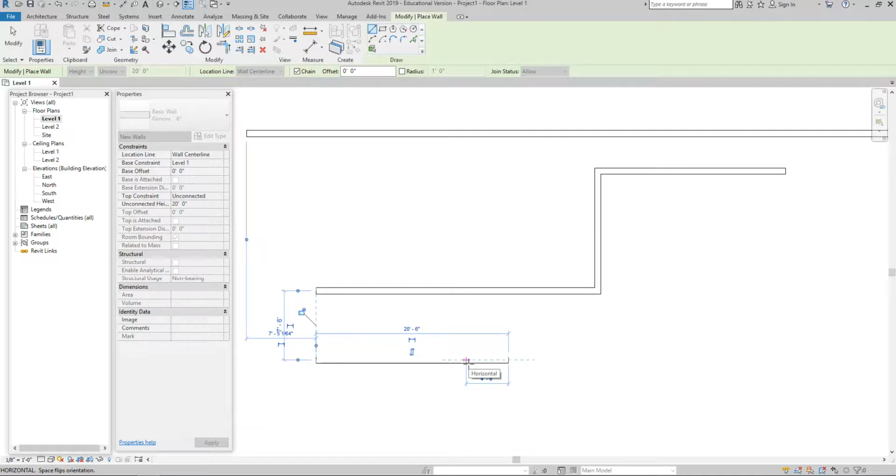Okay. Again, in AutoCAD, if you were to hit the enter key, right, in between that 20 and the 6, you'd get a hard return, which would execute the command. So this is something that those of you who use AutoCAD will have to get used to. The space bar is not forbidden in Revit, right? It doesn't create a hard return, and in AutoCAD it does. So what if I wanted to do something like 20 foot 6 and 1/2 inch? Well, I space them again. 20 space bar, 6 space bar, 1/2.